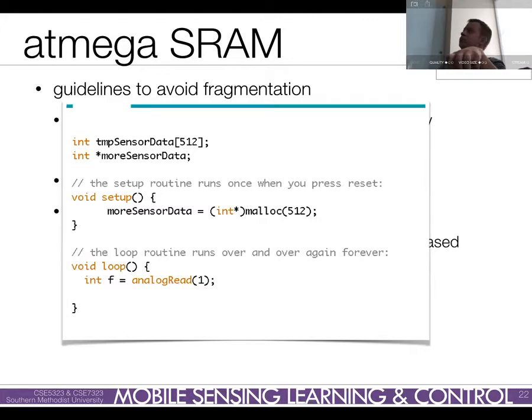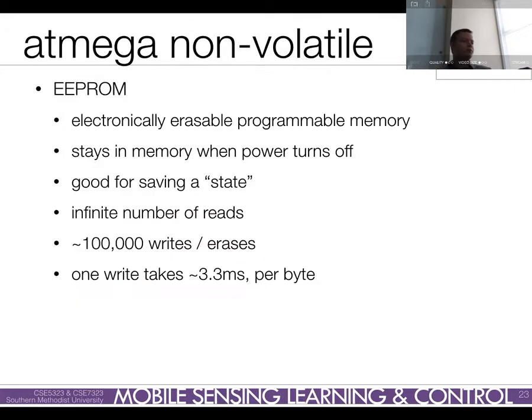Everybody see that? I've got 2 kilobytes. I'm taking up a kilobyte. Good. This temp sensor data, if it's really temporary, allocate it somewhere else. Do it locally. If I need to read in a bunch of sensor data, take the min or the mean or the maximum of that array and then return without doing anything else with that sensor data, then allocate it inside of a function.